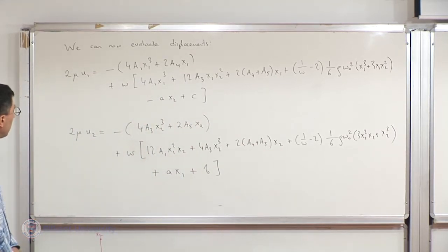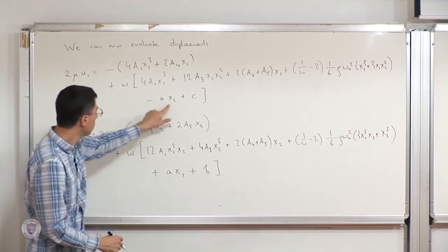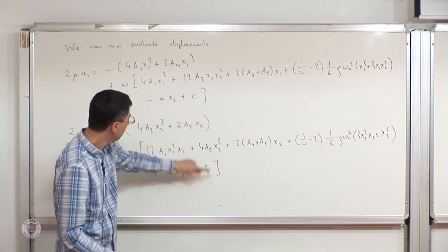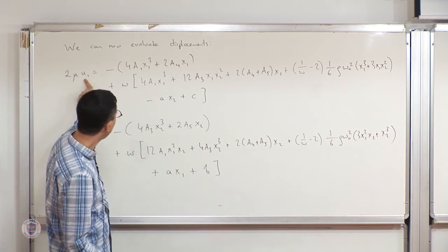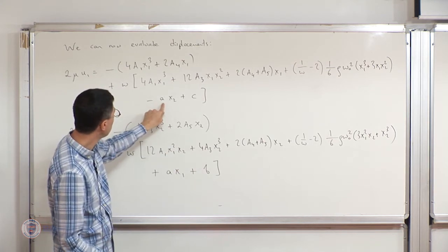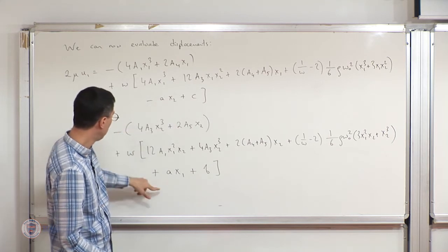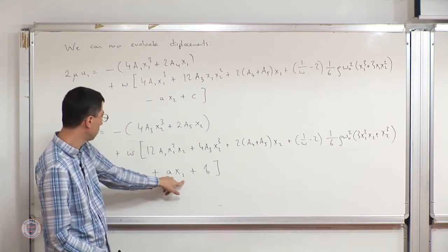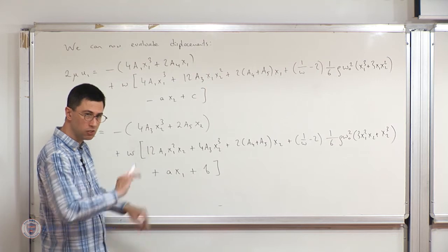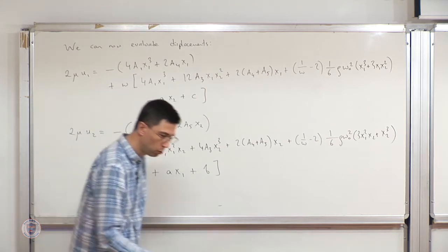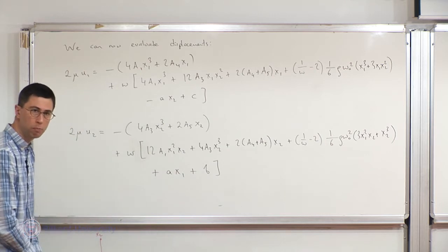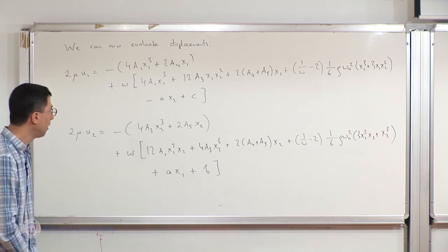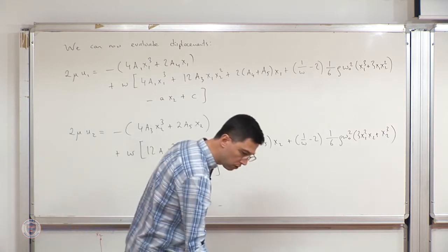Okay. So of course, we have some constants, and you will notice that these are associated with rigid body displacements. And for one component, minus some constant times x2. For two, minus that constant, x1. That somehow has to do with rigid body rotation. Okay, so I need to fix or constrain rigid body rotation and displacement in order to fix the solution itself.